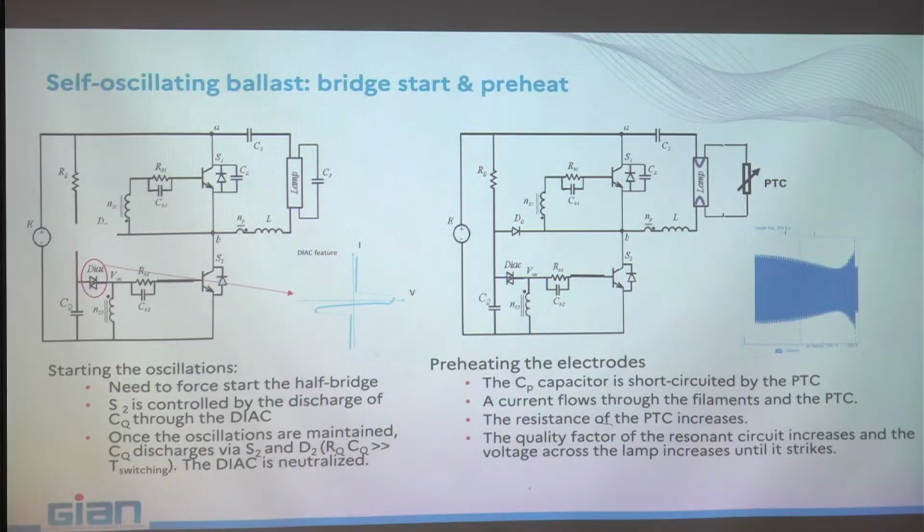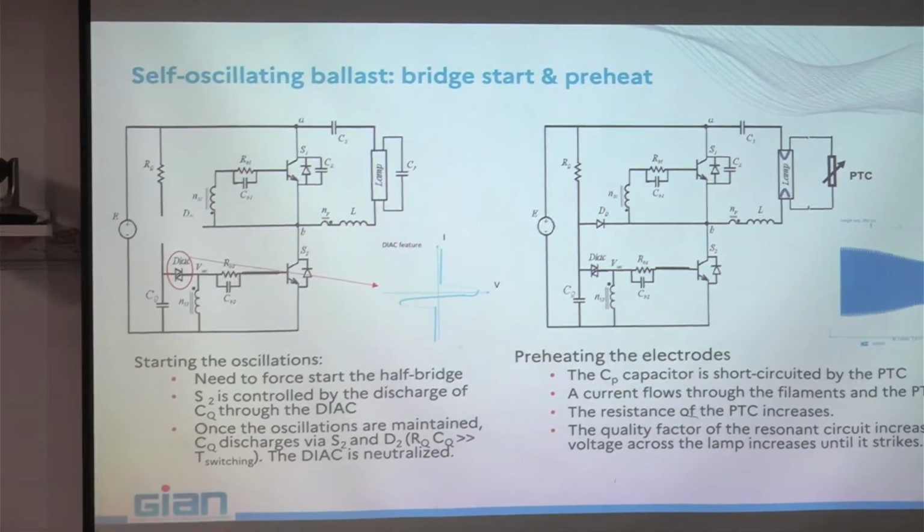And also you can go to very deep dimming levels because at very low dimming levels the electrodes have to supply many electrons, and there is the place where you vaporize more and more of the emitting paste. And if you keep the electrode hot enough, thanks to such kind of ballast, you continue respecting the lifespan of the lamp.